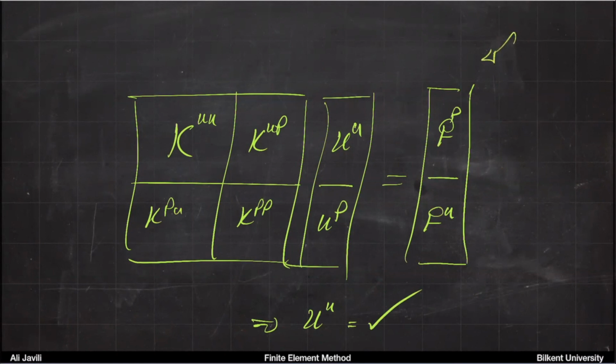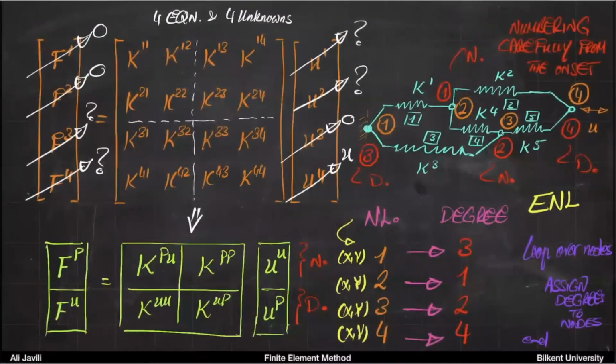Okay, this is just it. At that point it is only that static condensation, which we did for the one-dimensional problem. Remember, we did this in the past when we had a system like that. So if we had a one-dimensional system, we did this. Now, this system doesn't know if the bigger system is one-dimensional or two-dimensional. It doesn't care. It's exactly the same way that you are going to solve the problem. Okay, it's very good. I wanted to actually come to this point.